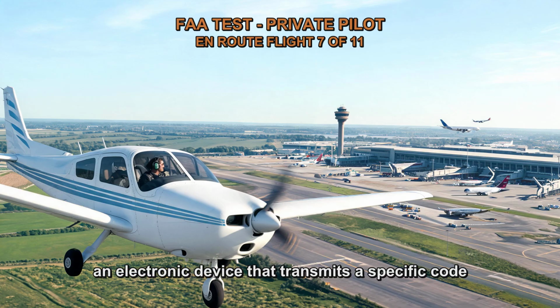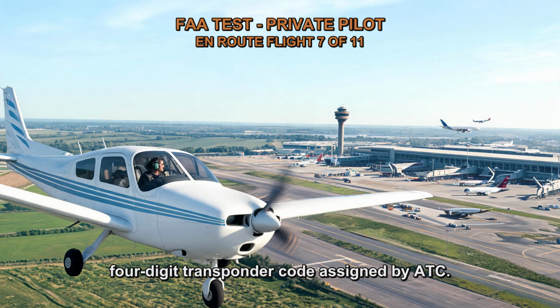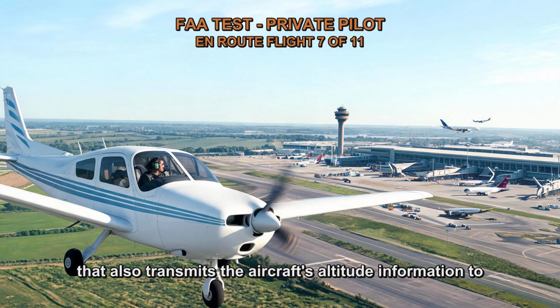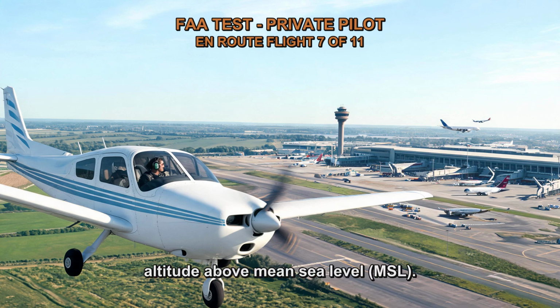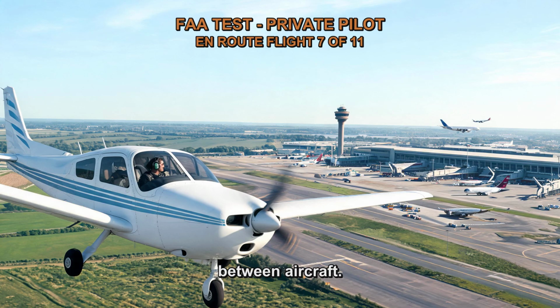A transponder is an electronic device that transmits a specific code when interrogated by radar. The 4096 code transponder is capable of transmitting a 4-digit transponder code assigned by ATC. This code helps ATC identify and track the aircraft on radar screens. Encoding altimeter. An encoding altimeter is an altimeter that also transmits the aircraft's altitude information to ATC. It provides accurate altitude readings, including the aircraft's altitude above mean sea level, MSL. This information is essential for maintaining vertical separation between aircraft.